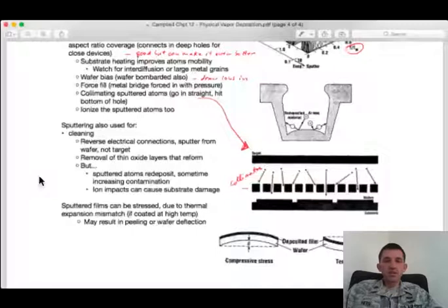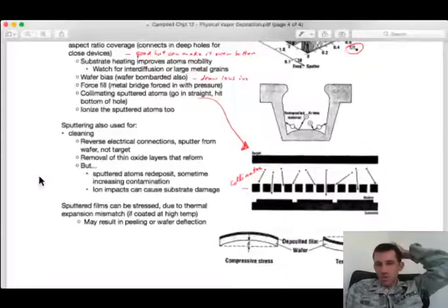There are other techniques that you can use. We already talked about, in etching, using, what's it called? Liftoff, right? Where that is actually intentionally taking advantage of the poor step coverage to enable you to selectively remove the metal. But here you can actually do kind of, I guess, the opposite, where you can force it in there by intentionally coating over the top of this, and then increasing the pressure to kind of collapse that film into the high aspect ratio feature and force it to fill in there.